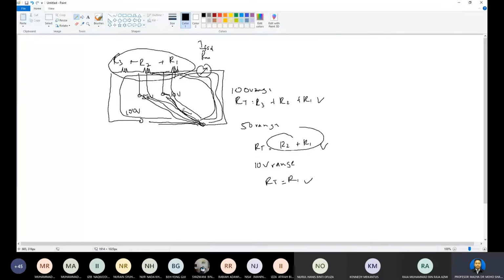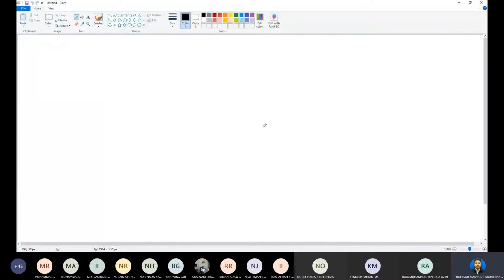Next we go for question 7. You can see on the figure, tutorial 2, question 7. The voltmeter on the 5 volt range is connected to measure the voltage across R2, 50 kilo ohms, in the circuit shown in figure 6, given R1 equal to 70 kilo ohms. Calculate VR2. First, A, without the meter connected. B, with the voltmeter having a sensitivity of 20 kilo ohms per volt. And C, with the voltmeter having a sensitivity of 200 kilo ohms per volt.